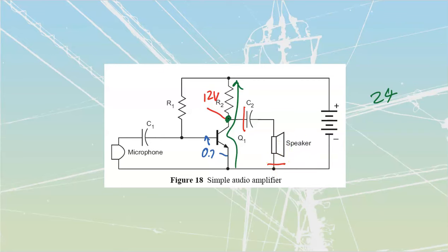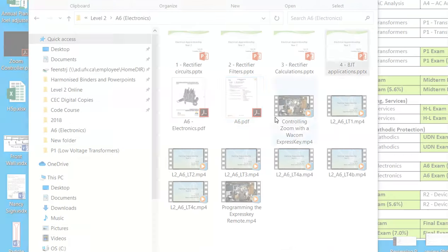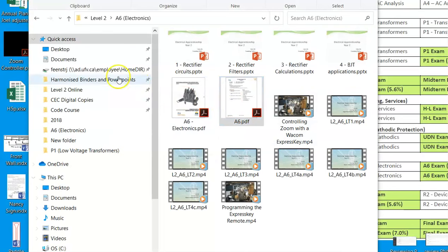But either way, it's this process of electrons that are going to tick, tick, tick, tick. They're going to leave from there and flow through the speaker. The speaker is just an electromagnet that's going in and out, and they're going to start to build up here. As they build up on here, what happens? Well, we get an equal and opposite reaction on the other side of that cap, and we drive electrons away. Those electrons are going to leave and go up to my source over there. This is all going to happen until we reach that value of 12 volts. Once we reach 12 volts, there's going to be no more current flow going to this cap, and no more current flow running away from that cap as well.